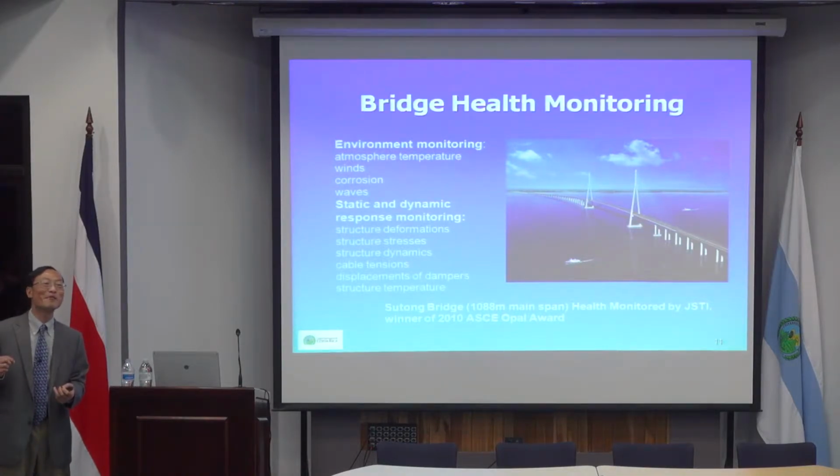But anyway, there's a model, if you study safety or reliability of manufactured products, one of the very simple models they call the bathtub model. For example, if you buy a car, very often you have a problem in the first month or something, and that's because of a manufacturing defect. And if you don't see a problem in the first 6 months, the chances you have a problem in the next year or so is very, very slim.